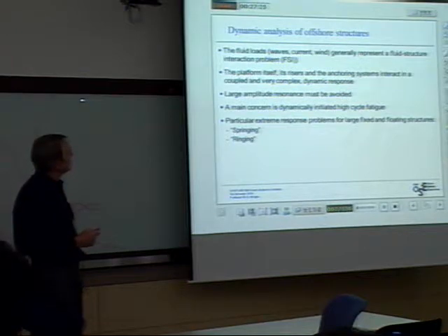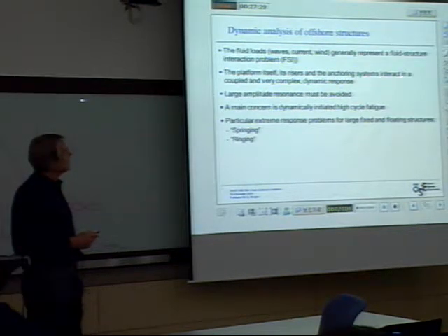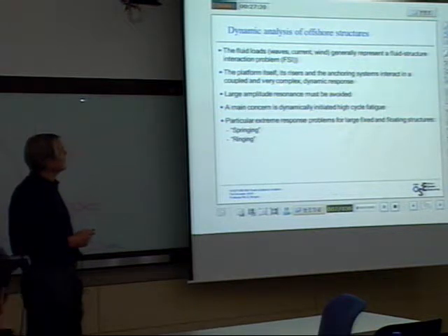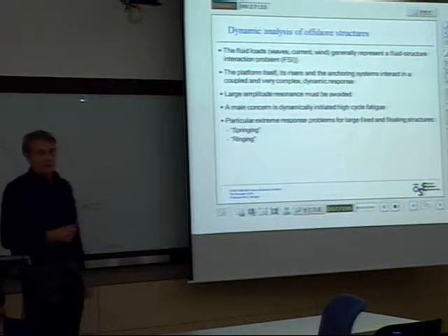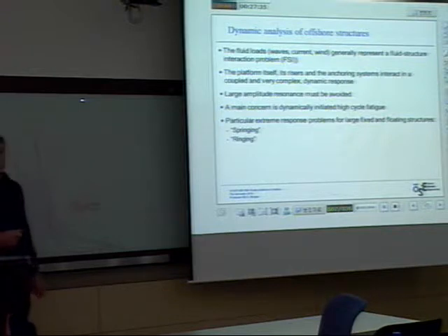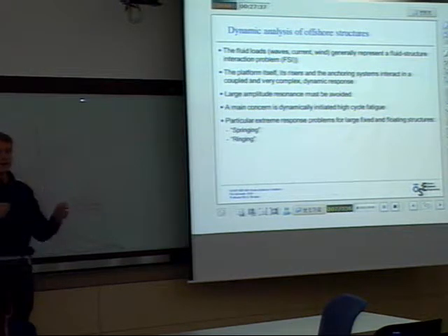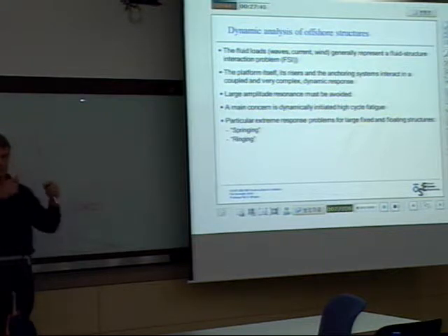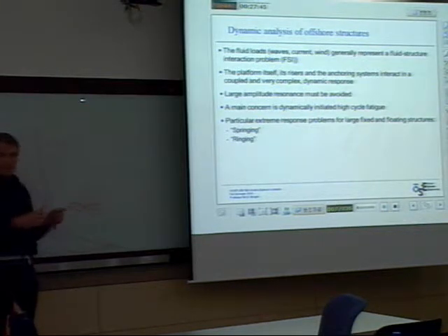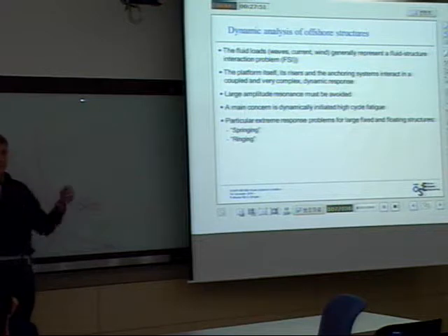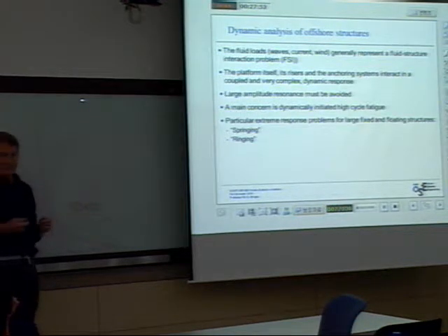So the platform itself, its risers and anchoring systems interact in a coupled and very complex dynamic response. So not only do you have a platform that is moving in the waves, you have an anchoring system, either catenary or a TLP type, and you have the risers, the conductors. All of this interacts.